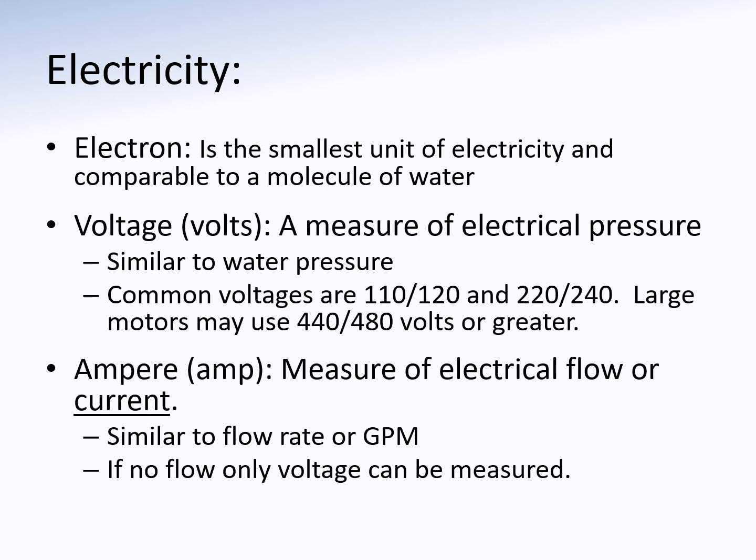Anytime you go over 600 volts, you actually have to have a certified electrician. I know that there's a lot of people who may be titled as an electrician at their agency, but unless they're a licensed electrician, they're not allowed to touch anything over 600 volts or greater.